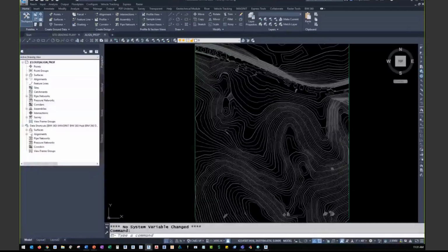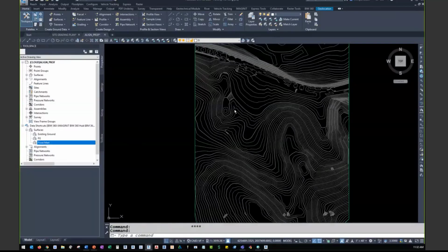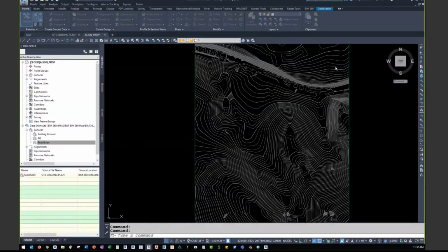So that ability to leverage cloud-based drawings, and this is another one here where I have alignments and profiles. This is a file that's being opened directly from the cloud, and it's identified there in the title of the drawing file. I've got my data shortcuts, again, path directly to the cloud. It says here BIM 360 instead of the C drive. And if I have any established data shortcuts also pointing up to the cloud there, I can create those references directly from the cloud locations as well.